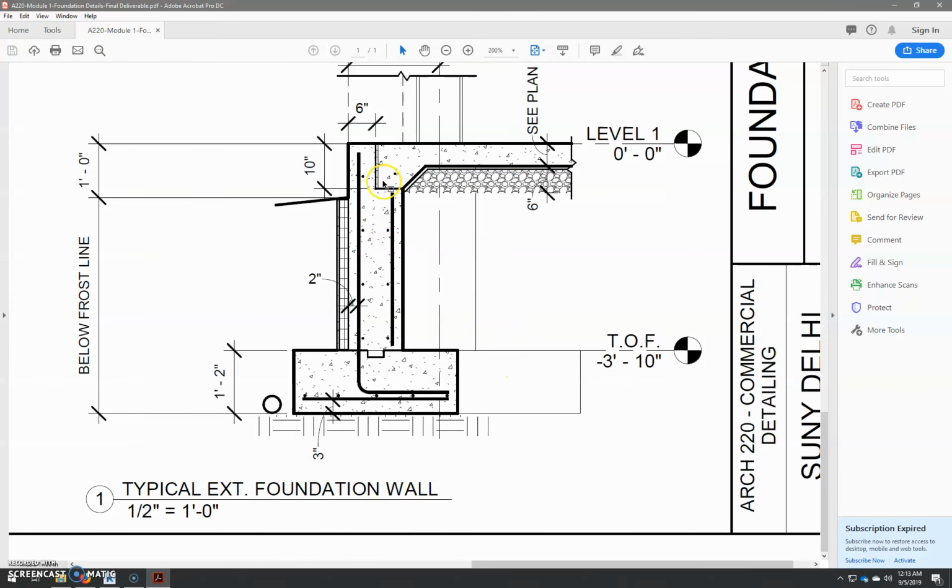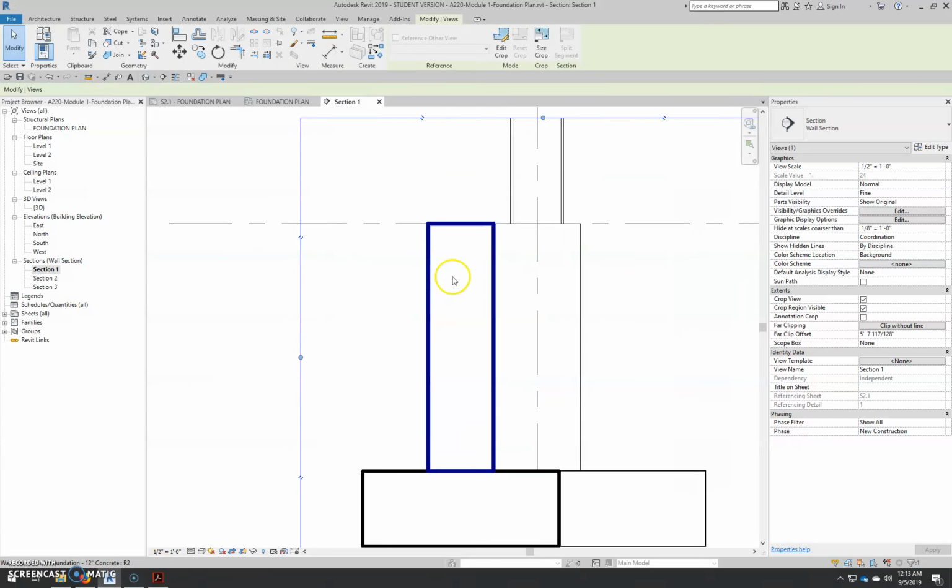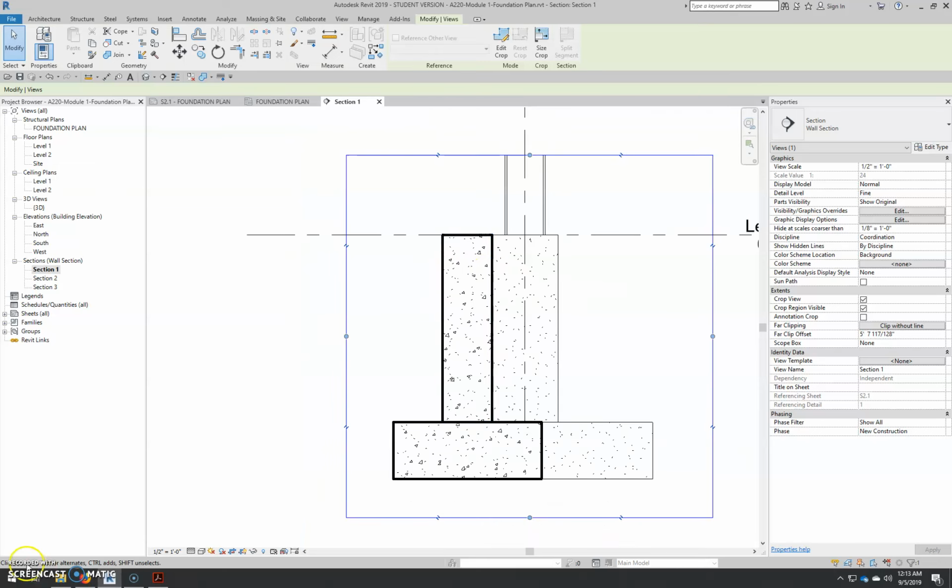The next thing that we're going to look at is we need to create this slab, but before we can create the slab, we have to create the ledge that the slab sits on in this wall. So we need to cut a section out of this wall. We are actually going to cut that wall out as well as build the slab and the thickened haunch all in our model. So those items will be 3-dimensional.